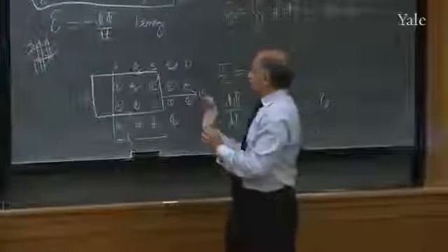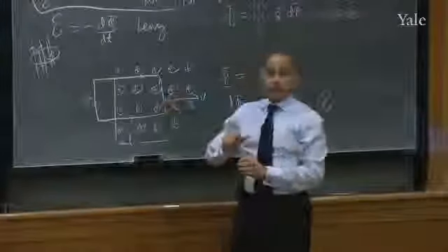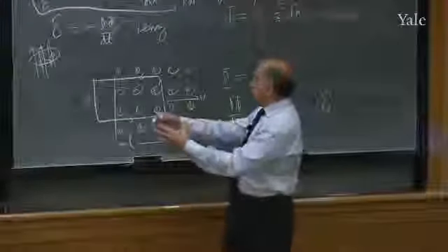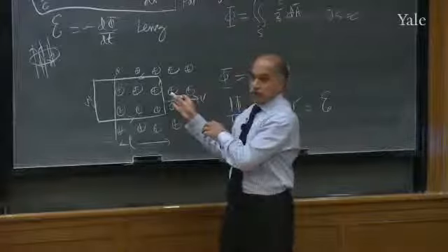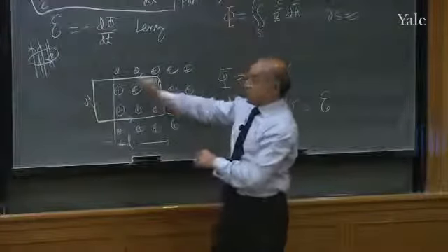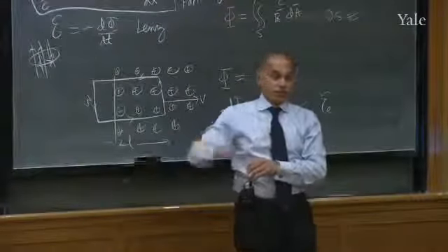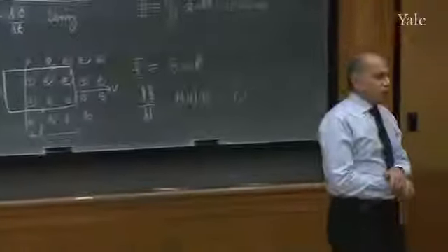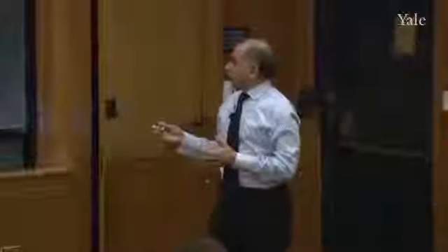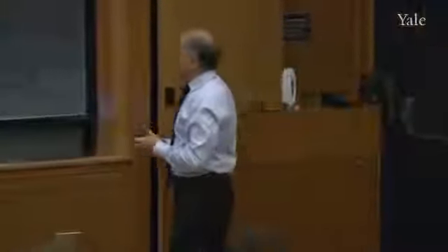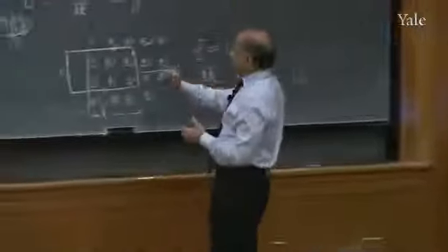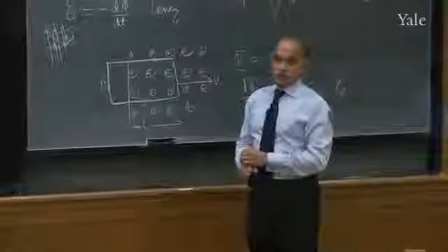You see that when the current flows like this, it'll start producing upward flux. In other words, you're getting more and more flux into the loop going into the board. To cancel it, I will produce flux coming out of the board. That's what the loop tells you. That way, you don't have to worry about all the cross products. At the very end, you ask, what's happening to the flux? How do I keep it from changing? And the answer is you keep it, in this case, from changing by producing flux coming out of the blackboard.